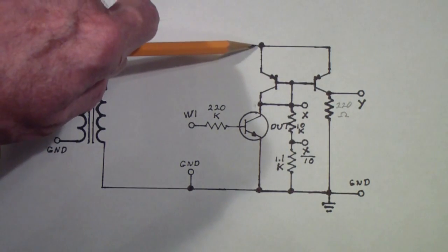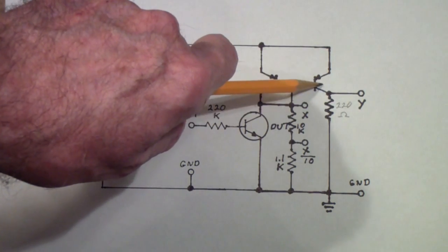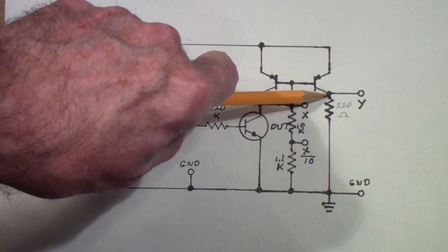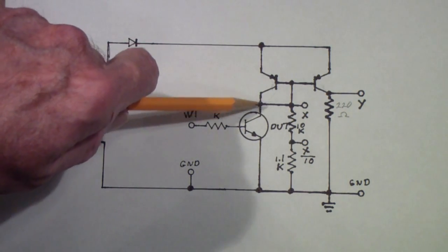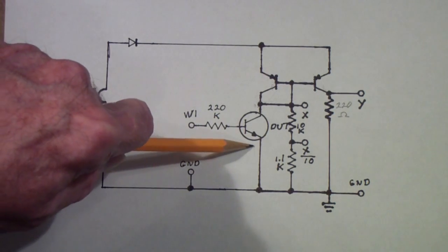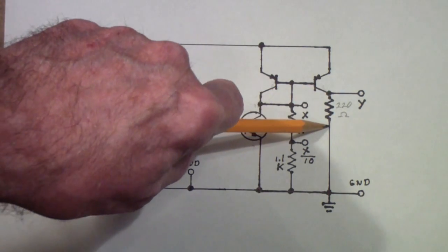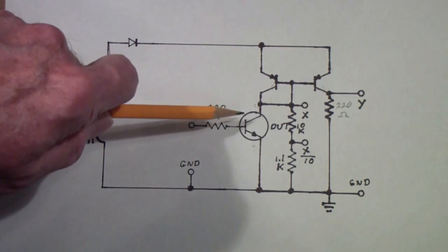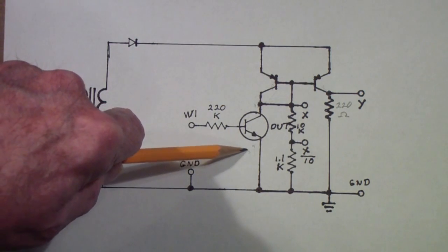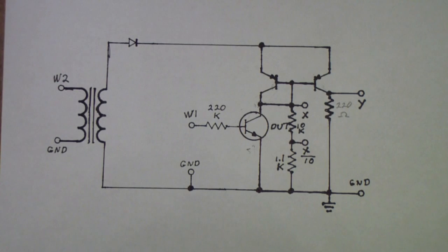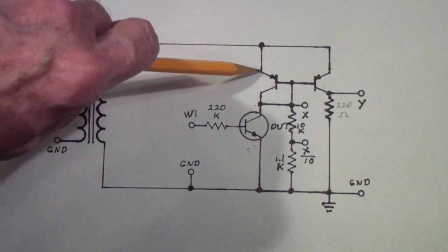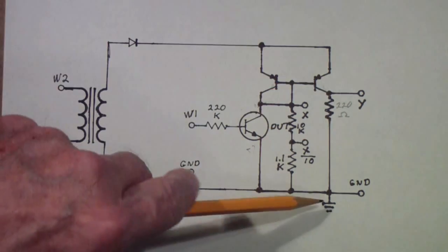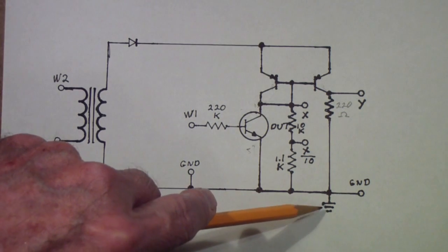The two emitters are tied together, and therefore the current out of this collector will be equal to the current out of this collector. Well, the current out of this collector is whatever's flowing through this transistor. So the current through this resistor mirrors the current through this transistor. Now, why do we do this? Well, not only do we get higher output impedance this way, in other words, we eliminate some of the effects of that finite resistor, but we also are now able to reference everything to ground.